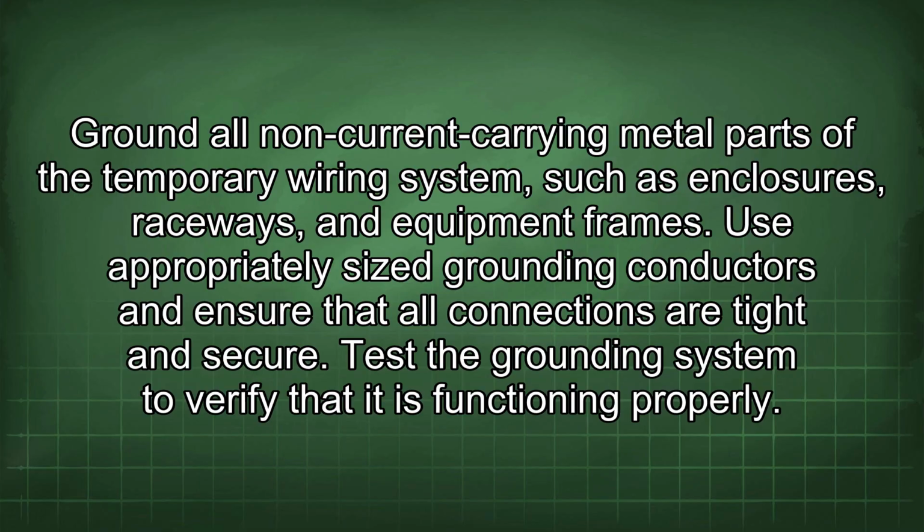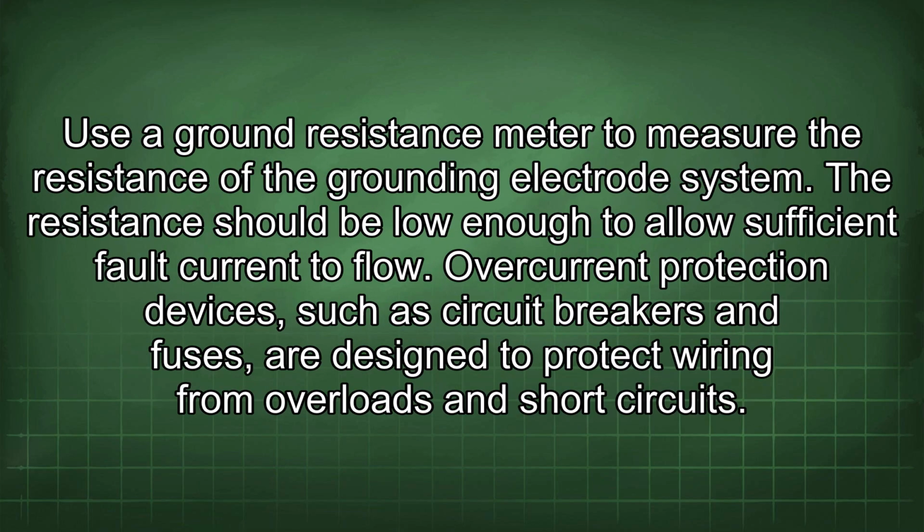Test the grounding system to verify that it is functioning properly. Use a ground resistance meter to measure the resistance of the grounding electrode system. The resistance should be low enough to allow sufficient fault current to flow.